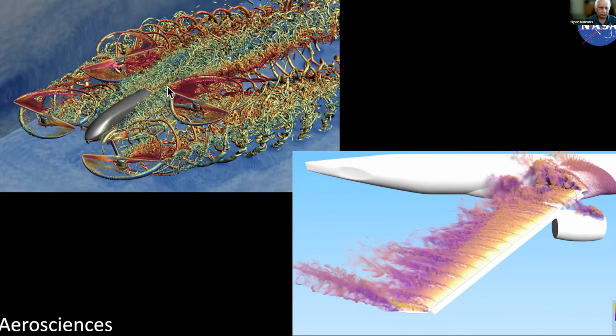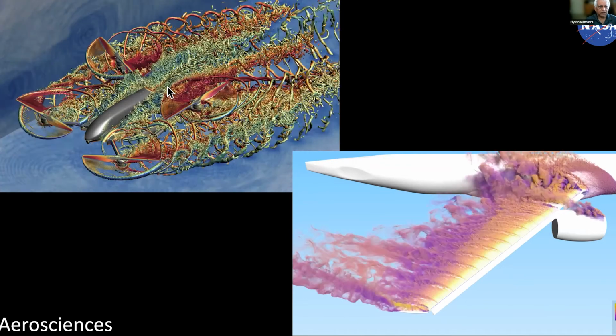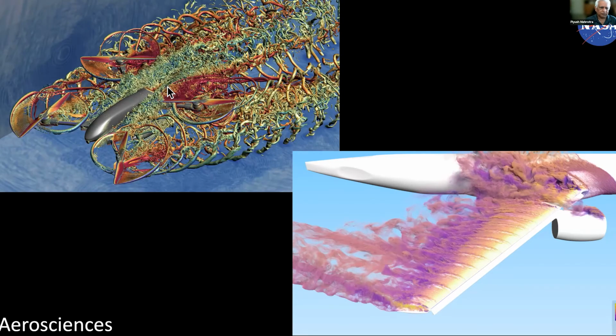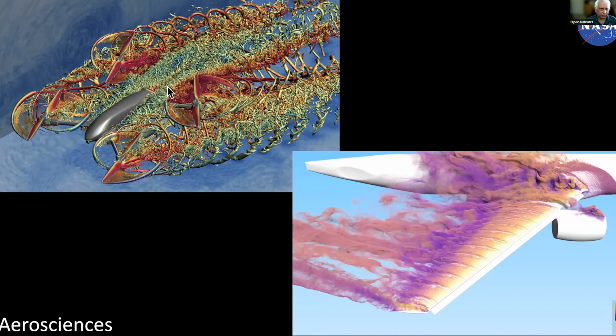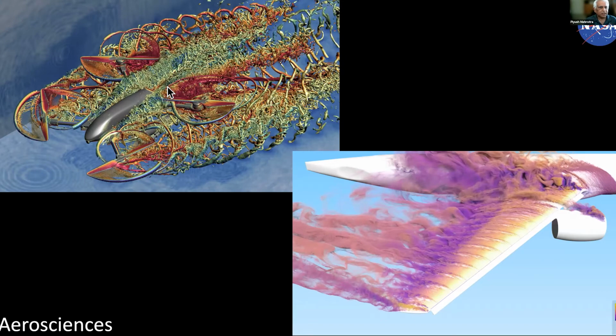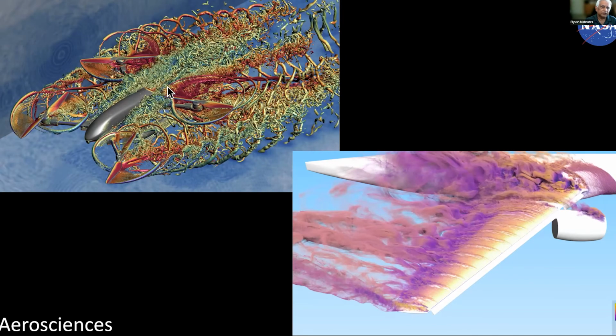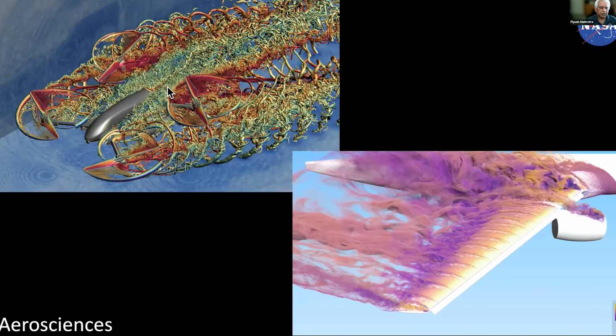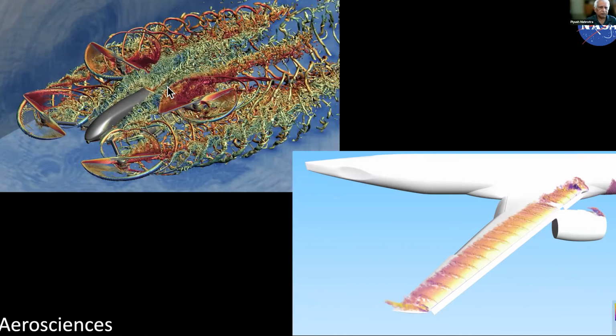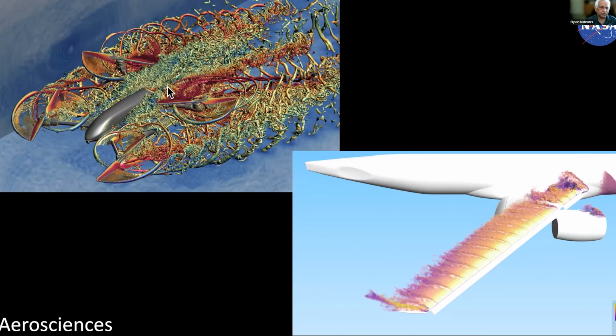Most of the noise that is generated by the blades is fairly easy to predict. It requires only very low fidelity tools to do it. But noise that reaches the earth, broadband noise as it's called, which is high frequency, low bandwidth noise, that's much more difficult to predict. So they are developing tools. This is particularly a group in my division, the LAVA group, which has been focusing on using lattice-Boltzmann equations to do the simulations that you see on the top left.